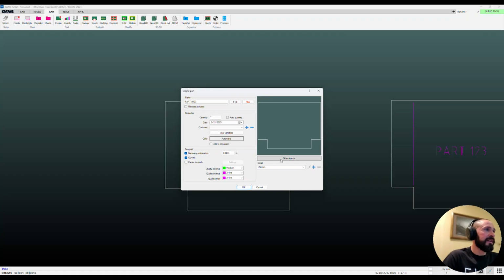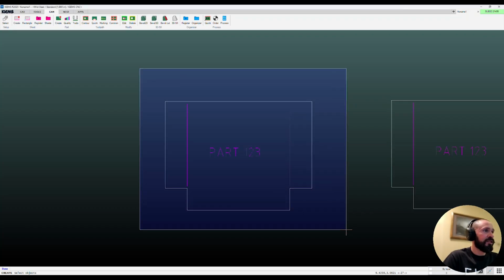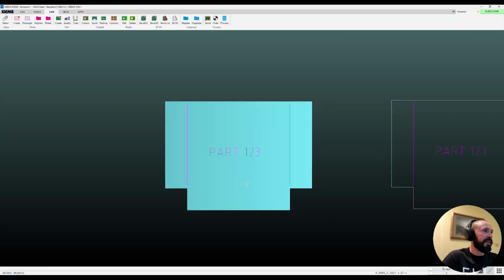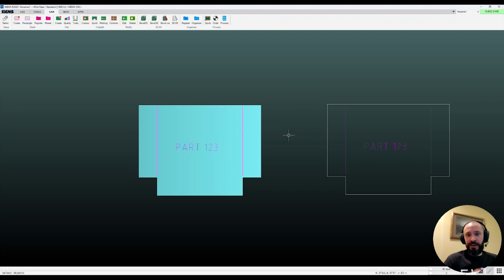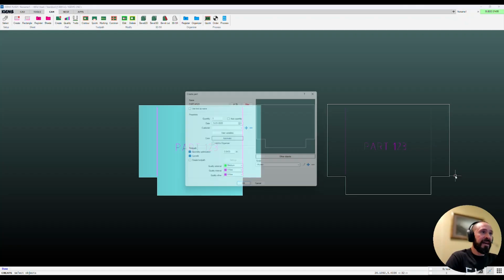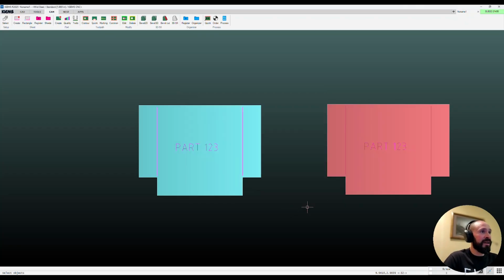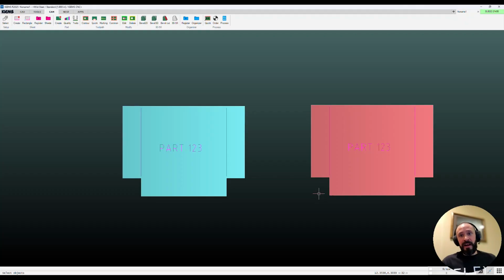So I'm going to click this Other Objects button. Just grab everything again, and you'll see my Create Part dialog pulls in those open contours as valid geometries now. So let's click OK. Now, let's say you're cruising along and you forgot to do that. We'll step through that again as I create my part, hit Enter. I forget to select the other objects, and I just hit OK.